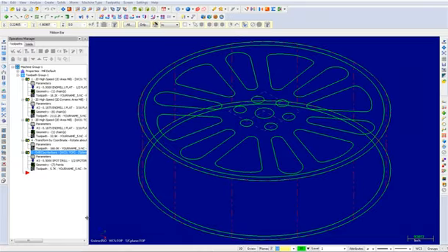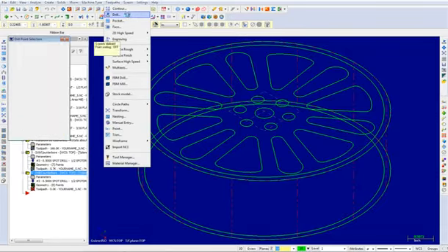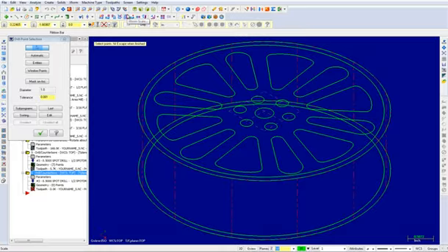We will now drill the 1/4 inch holes to a specified depth. Again, select Toolpaths, Drill. When the drill point selection dialog box appears, choose the last button. This option will automatically select the hole for you based off the selection from the previous drill operation. Once complete, select the OK button to exit the drill point selection dialog box.